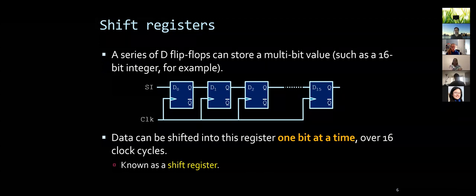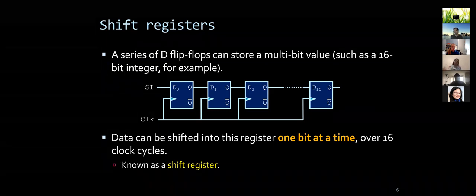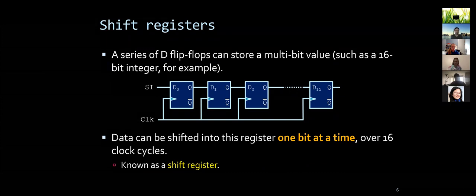That's what I want. So here you do the same type of trick, but instead of having two gates, I had 16 D flip-flops, right? It's called a shift register because the value propagates one cycle at a time. It's not that the water goes through all of them right away, it goes one cycle at a time. So it has its advantages and disadvantages. It is relatively simple to implement, but remember, it would take 16 clock cycles for the value to propagate. So if I want to store something with this, it's 16 processor cycles. So it's not super fast, right?